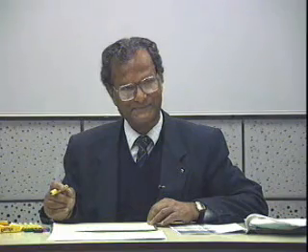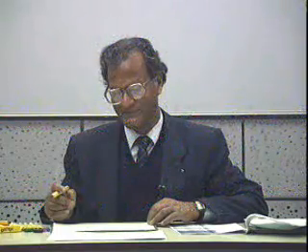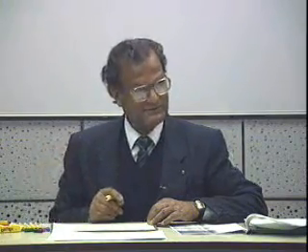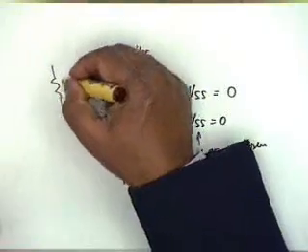Could you choose VSS equal to 0? Why not? No, but the drop in R sigma, how can you avoid that? VGS should be negative. So VG is 0, VS should be positive. Now R sigma, what I am saying is, could this be taken to 0?